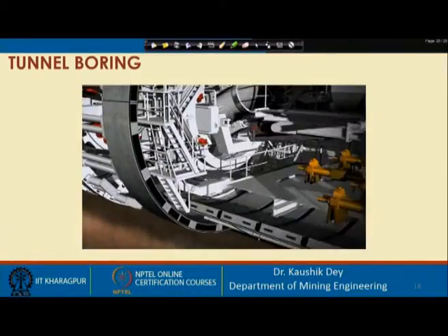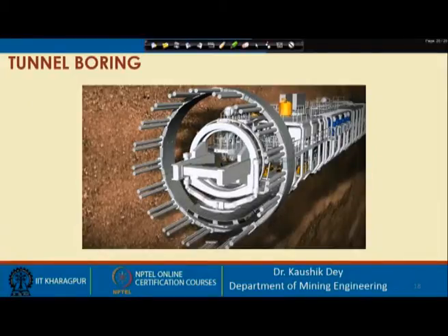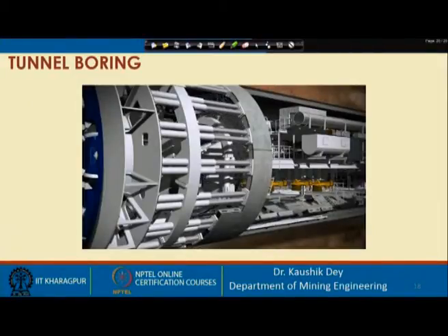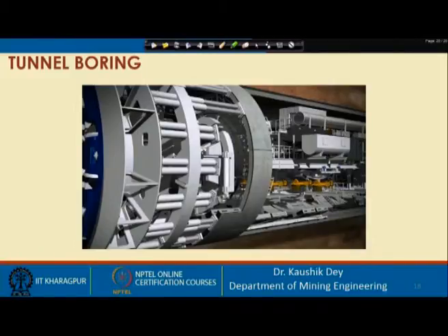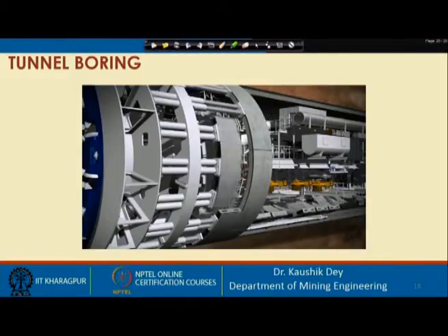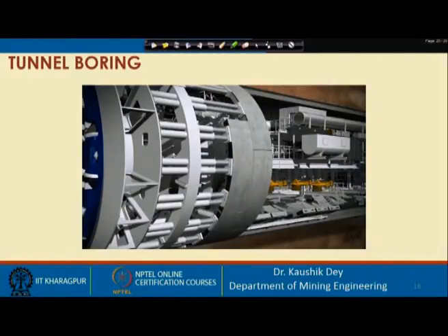You can see these concrete segments are fed by the segment feeder and lifted into place using a vacuum. The support systems are also being placed automatically. The hydraulic cylinders are temporarily retracted in order to provide enough space for the new segment. So, that will be placed automatically, and it will be fixed.